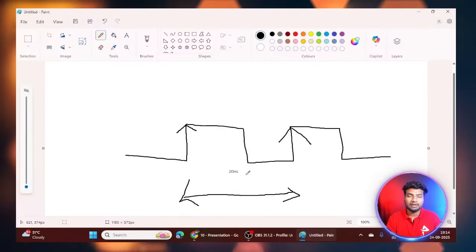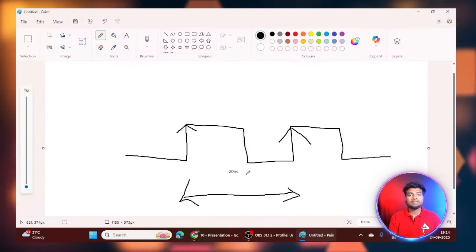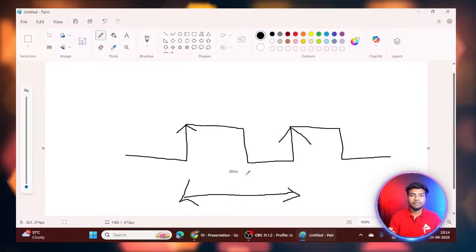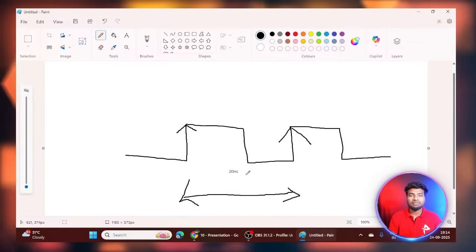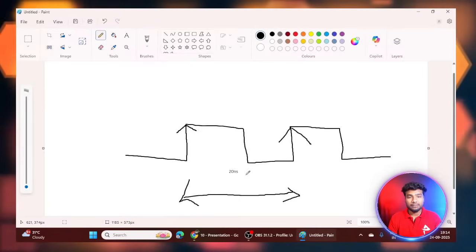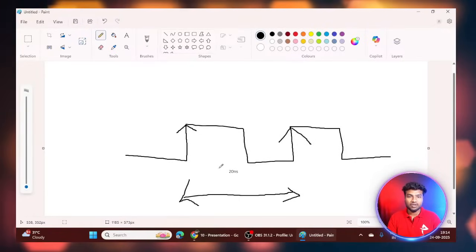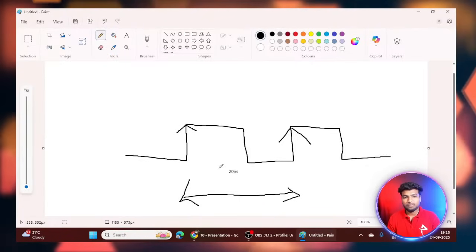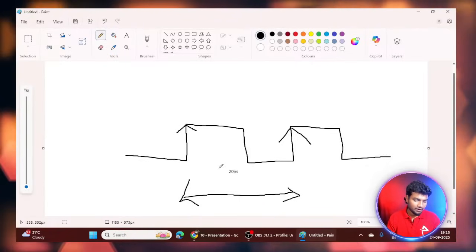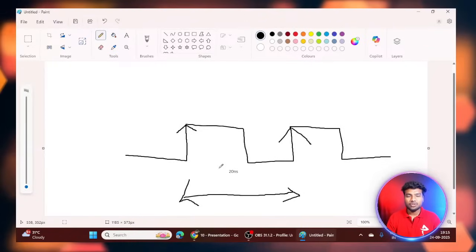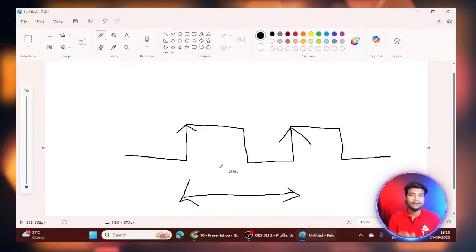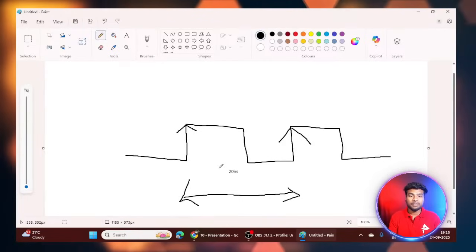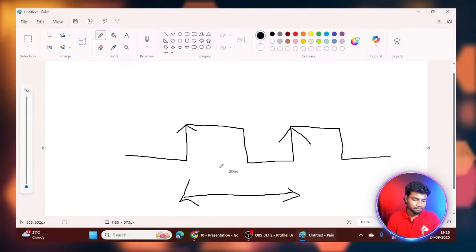megahertz. If it is 100 megahertz, the time taken will reduce. Why? Because when frequency increases, time is reduced. So with a 100 megahertz clock, the time taken for one clock cycle is 10 nanoseconds: 5 nanoseconds off time and 5 nanoseconds on time. Okay, it's clear for you? Yes, it's clear. Thank you for the response. So this is how we can find the frequency based on the time, and also the time based on the frequency. It's vice versa.